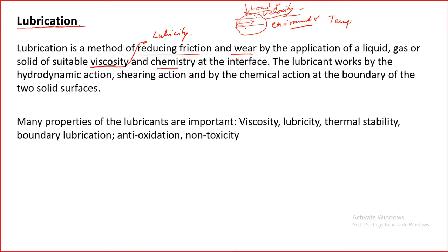So the very first solution we look for is lubrication. As I said, viscosity plays a very important role. We will study how viscosity is related to the shear stress. So viscosity basically helps to separate the two surfaces. Let's say we have two surfaces and there is liquid in between, but since we have to apply some load, this liquid can get squeezed out under different situations. Let's say flat on flat or non-conformal. In this kind of situation also, if the load is applied, the liquid can get squeezed out. So it will not work. Even if you lubricate the surfaces, they will not work.